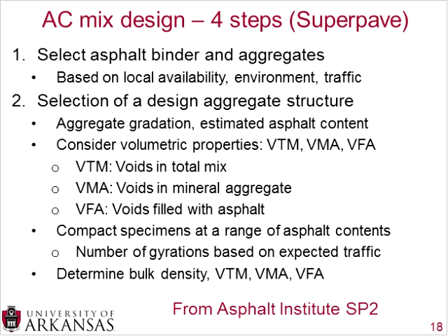And now going over to the AC mix design, this is divided into 4 steps, and we'll follow the Superpave mix design method. Now, I fully realize that the Marshall mix design method is used, especially with smaller agencies, counties and towns and such, and also if you're on the West Coast, you may use the Hveem mix design method. But for the purposes of this presentation, I'm going to focus on the Superpave mix design method, which is used for a lot of the interstates and a lot of the larger DOT projects or larger city projects.